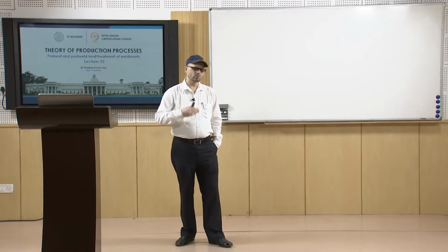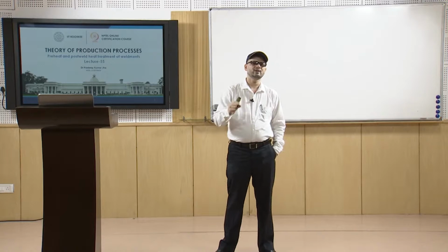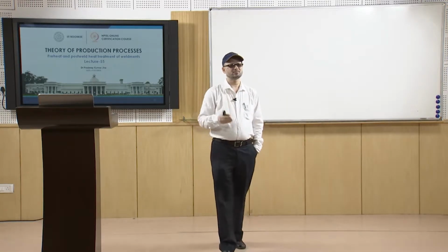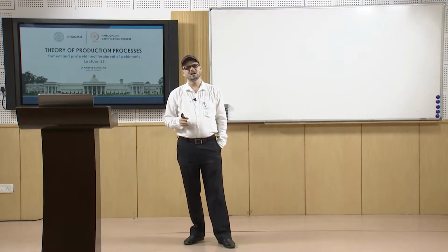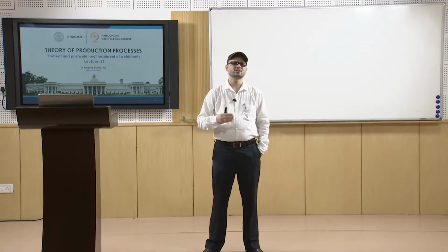So when welding under these low temperature conditions, there is a challenge, and you need a special provision of pre or post weld heat treatment so that you get satisfactory results.